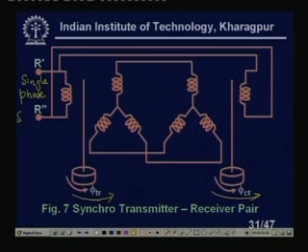Single phase supply I am giving here. Okay, so previously you would see this type of system used when digital clocks were not commonly available, some 30-40 years back. People used this type of synchro in railway stations and airports, where all the clocks should show the same time. They have a master clock connected through a synchro transmitter to several slave clocks.